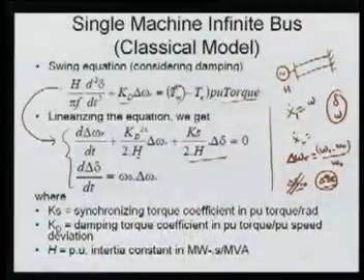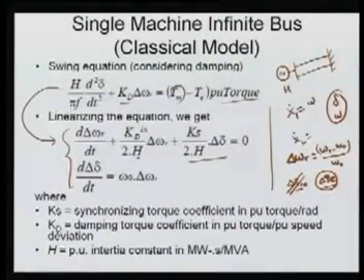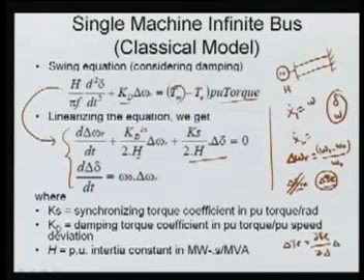What is this Te? If you are differentiating this Te, we can get the change in Te. Here the change in Te will be the partial derivative of Te with respect to delta, times d delta, in per unit. The Te will be equal to your Pe, and it is E into V divided by X sine delta.